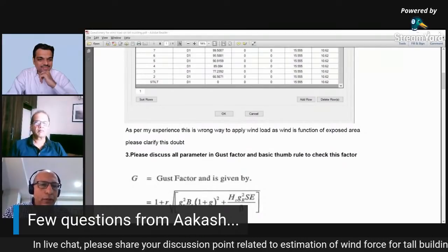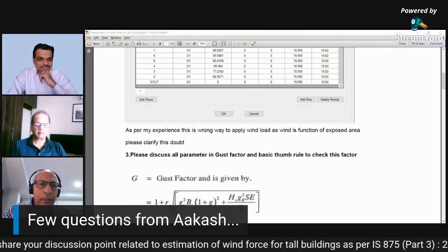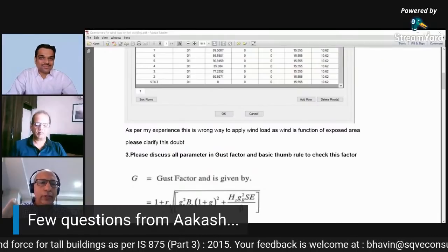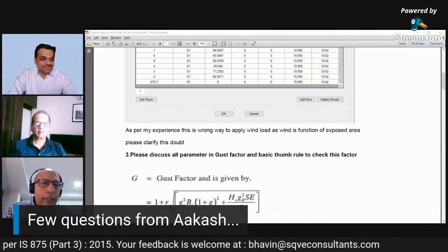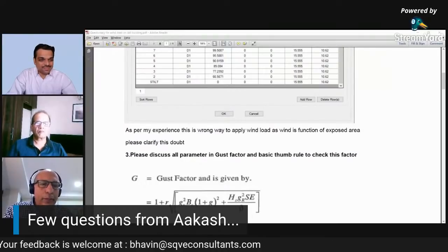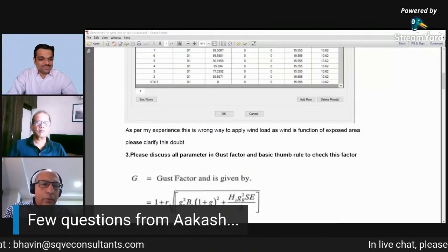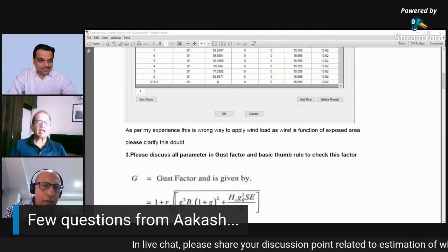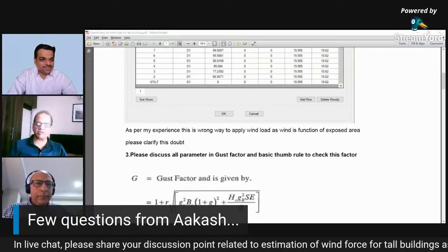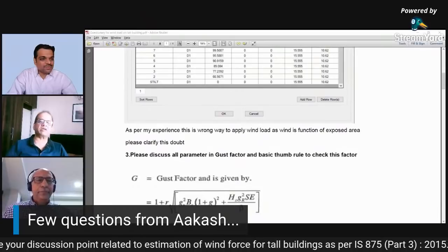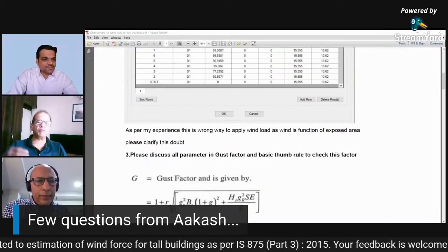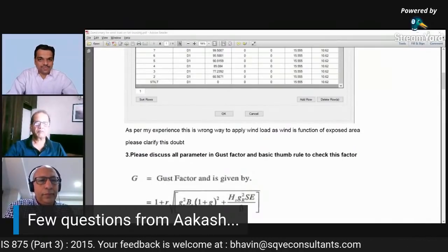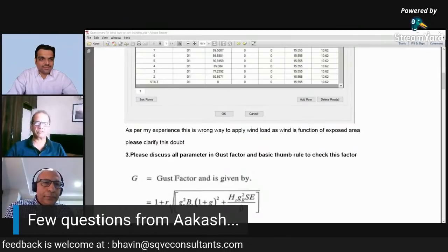And as Dr. Gupta did suggest, I think it's a good exercise to see what happens if, for example, you split this point load that's at the center to 4 equal loads at the corners. You'll probably see more of a difference if it's low to mid rise, but probably not much of a difference for a high rise building. A building which is flexural, basically a tall building which is primarily behaving as a vertical cantilever, more than 150 meters tall, I believe. There, the difference may not be significant. But below that, yes, there would be a difference.